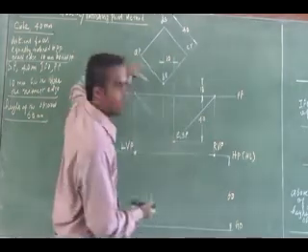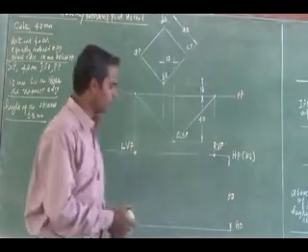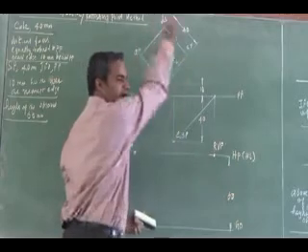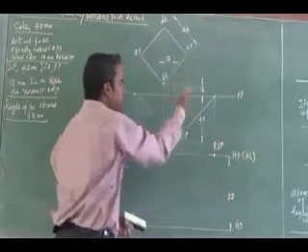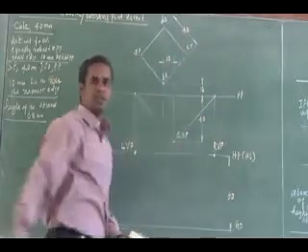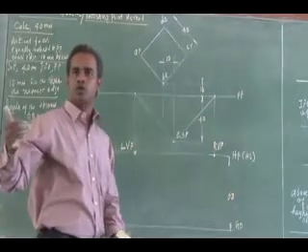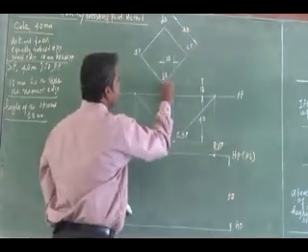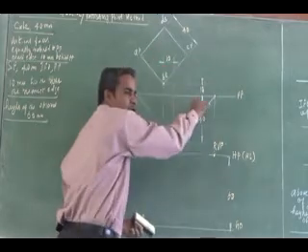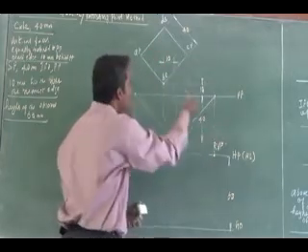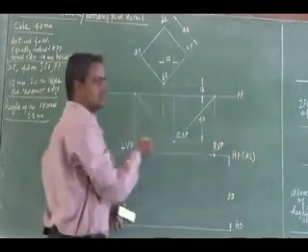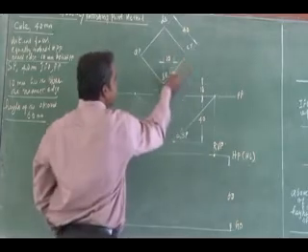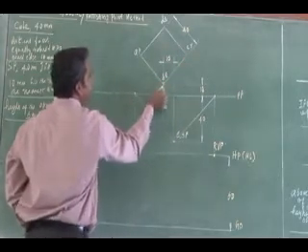So the true height of the cube, I am going to draw it from the picture ground plane. From this location, I don't find the true height for all the vertical edges, because all the vertical edges are behind the picture plane. So to draw the true height of the cube, I will extend this BQ corner this way, parallel to the left vanishing line, or parallel to this face. Either I can extend like this or like this, it's up to you. I am going to extend in this manner.